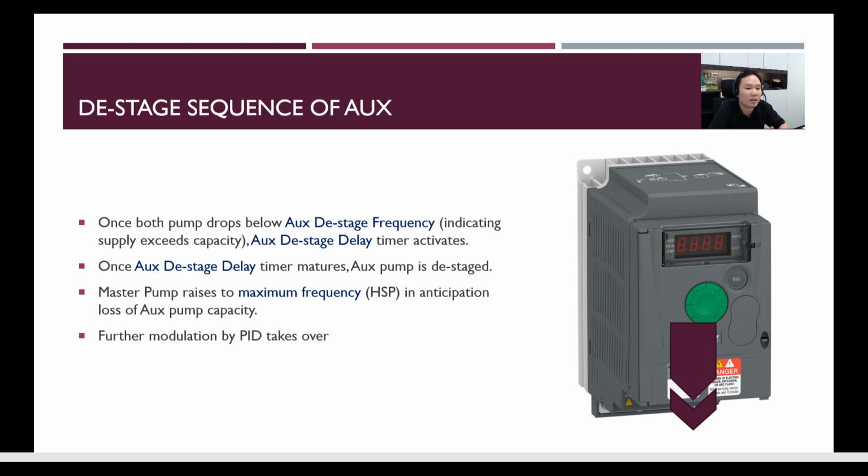Once this timer matures, the aux pump is destaged. How long do you want the timer to go? This, I believe, very much depends on your application. If you are having very frequent changes in demand, you might need to delay it for longer so that your auxiliary pump doesn't kick in and stage and destage in a very fast manner.